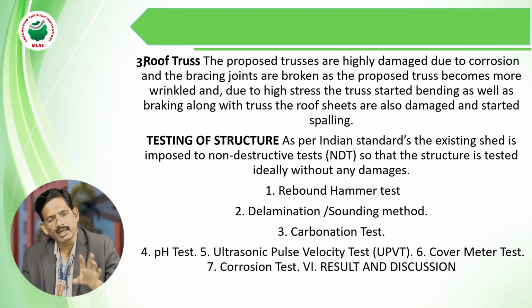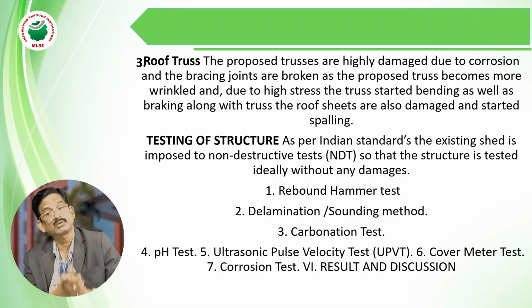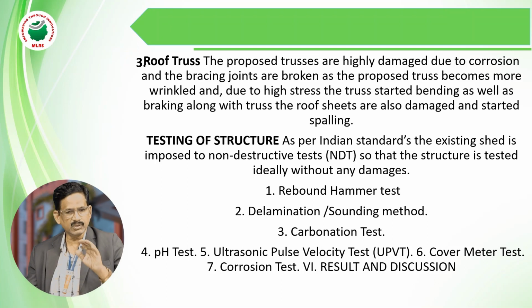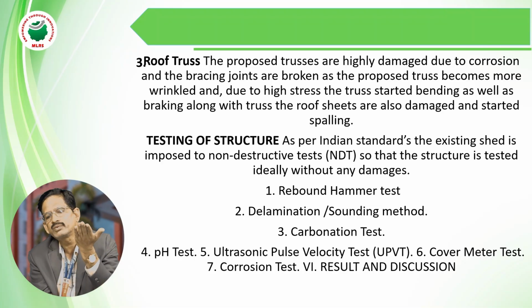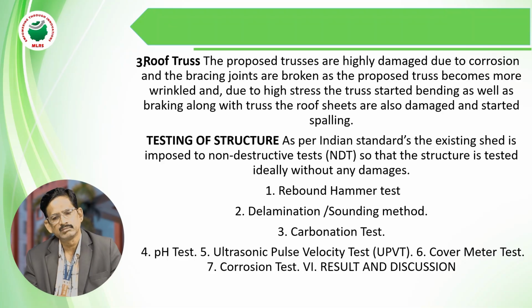I have already said that there are the balanced section, the under-reinforced section and the over-reinforced section. Don't go for an over-reinforced section, because the code will reject it. You don't want to go for more reinforcement, and you don't want to go for less reinforcement. You have to provide whatever reinforcement is required. Otherwise, negative stresses will develop inside the structure only.